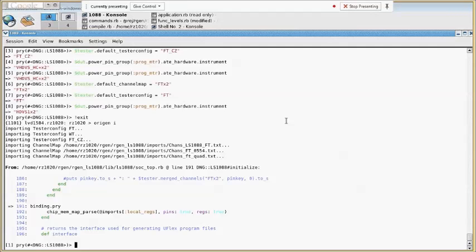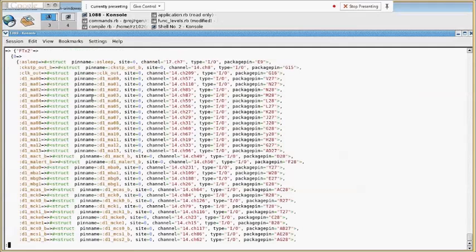First thing first, I'll show channel map. In this case, I'm just taking the channel map from IG-XL and loading the entire content into Origen. You can see I have size. Well, hang on, let me get that real quick. If I do .keys, you can see I have three sets of channel map I loaded, right? If I do that, you can see I have size 0, and if I keep going, I have all the pins with a pin name, site number, channel, etc. All that is in there, okay?